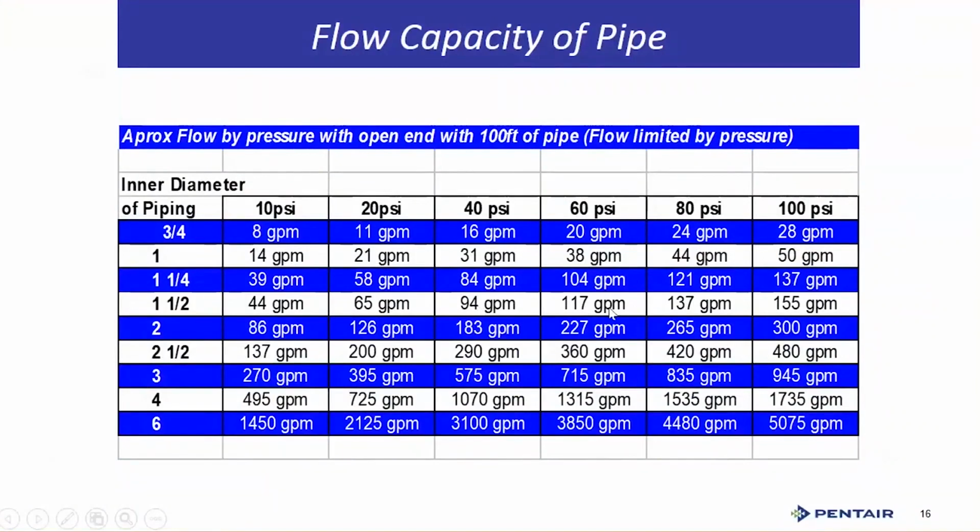So we need to be here with the plumbing size in the building. Well, guess what? If our customer's equipment requires 50 GPM and they've only got 1 inch lines here, there may be some interesting plumbing work for that customer in the future. So understand, hydraulic envelope is critical to success in water treatment.